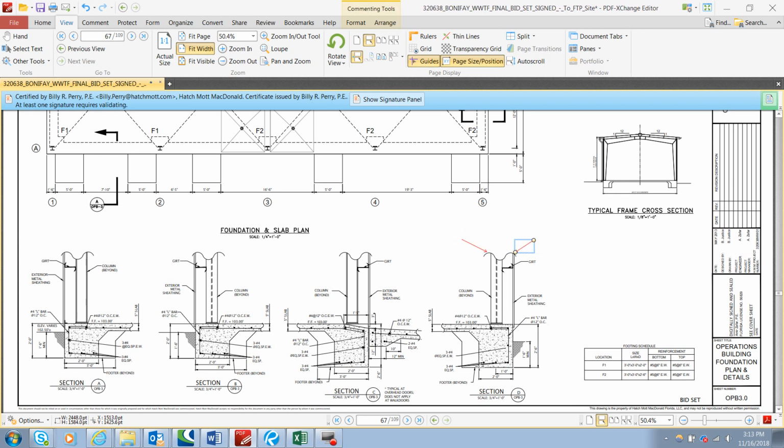This is the detail, what we're trying to show, the section. Remember our discussion of sections and what these particular things mean. As we drew the section, our interest is this particular area here. It's not anything above it. Now we have columns and roof lines and all of that stuff above it. The work continues, but we're not showing that, and we need to break the view here by using this. So we have breaks on this, here. So anything above this line is not shown. That just is a finishing point, if you will.